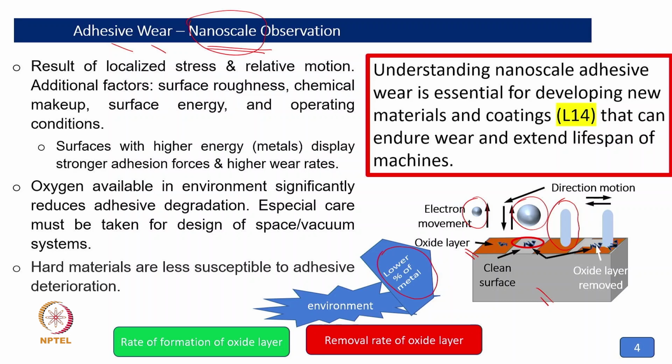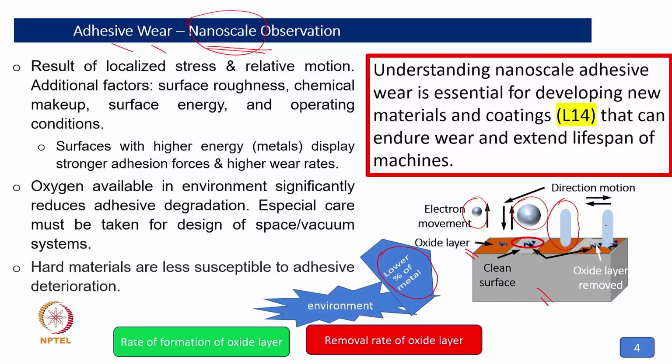This is acceptable to us, but going beyond that, when only virgin surfaces, say virgin surface 1 and virgin surface 2, glide or slide against each other, then adhesion occurs because of molecular interaction or exchange of electrons. Then a cold weld junction occurs, and to break the cold junction, either we really require a lubricant or there will be a huge wear rate. So these things are related. That's why we are trying to interpret the same thing in a slightly different manner.